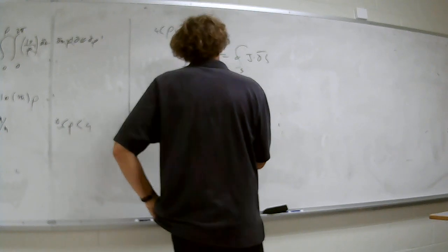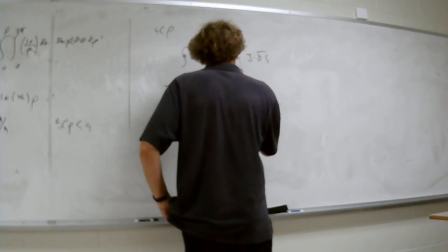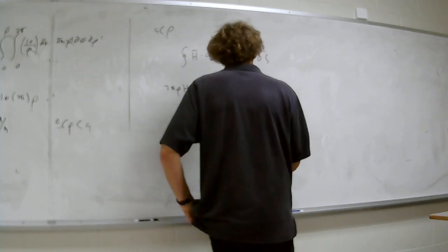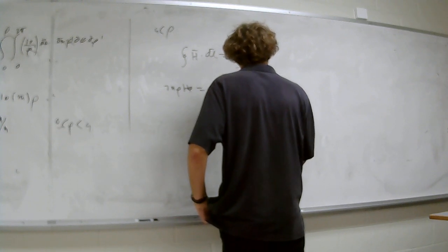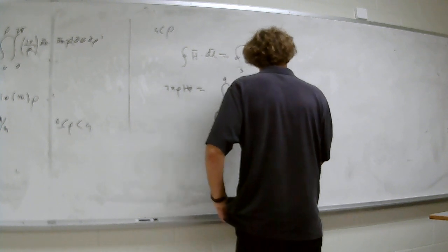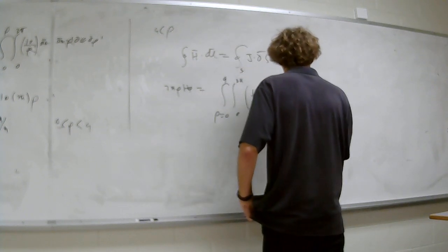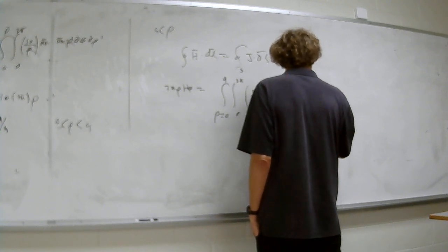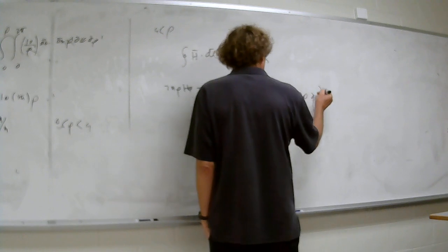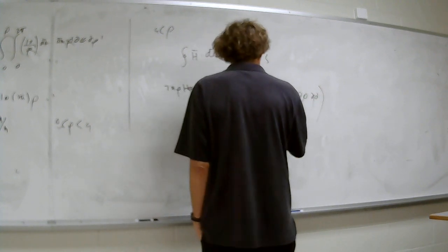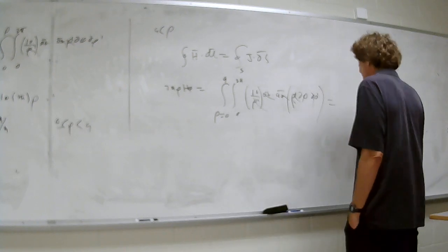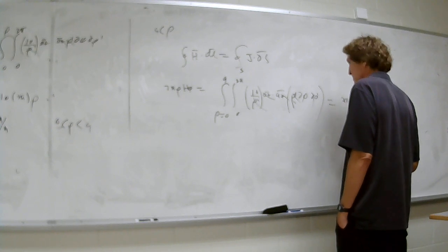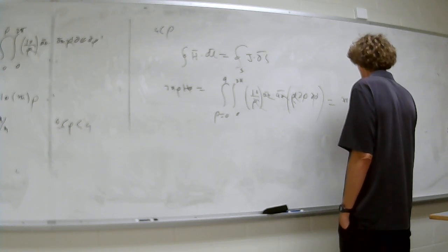So here, it's going to be the same deal. You're going to have an integral from 0 to 2 pi. Now this goes from rho equals 0 to A, and it's going to be 10 over rho az dot az, and it will be rho d phi d rho. Technically these are primed, it won't matter, they cancel, az dot az is 1. So I end up getting 2 pi, and integrating rho prime from 0 to A is just going to be 10 times A.